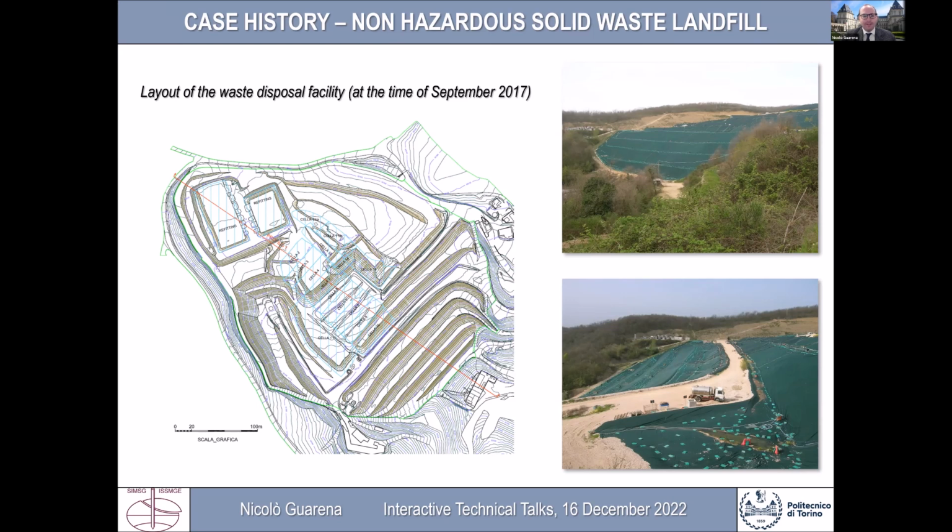The landfilling activities started in 1995, and the geotechnical consultancy was commissioned by the landfill operators in 2017 to assess whether the landfilling activities could continue without the risk of triggering instability phenomena until reaching the maximum authorized capacity. The results of large-scale direct shear tests, which were carried out on representative samples of the most critical interfaces of the landfill bottom liner, pointed out the existence of very low values of the angle of shear resistance ranging from 10 to 15 degrees, which needed to be properly considered in the landfill stability analysis.